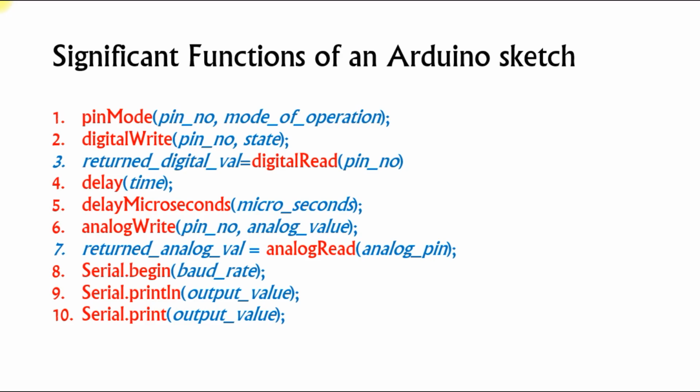This is the baud rate, because my laptop is working at a different frequency and my Arduino is working at a different frequency. Each device is working at a separate speed, right? So we are telling a common speed. If you want to make the data transaction without any loss, without dropping any data packet, while sending as well as receiving data between Arduino UNO and laptop, you have to set the same speed on the two devices. So the baud rate is fixed.